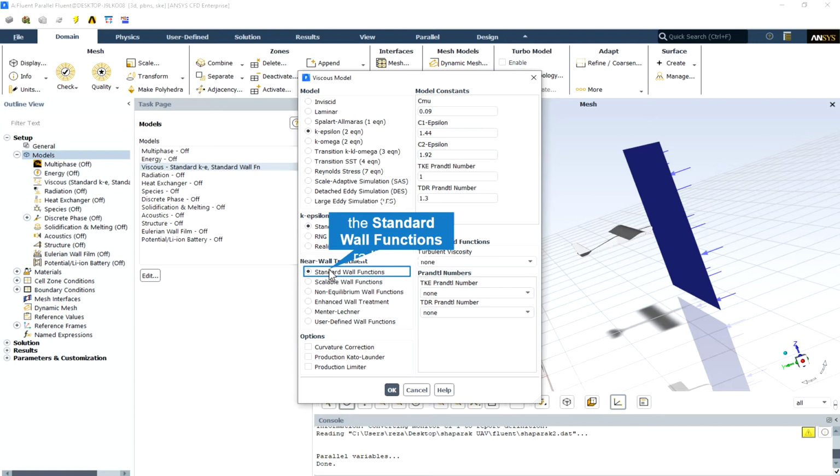If the k-epsilon turbulence model is used for the simulation, it is not possible to simulate flow vortices near the walls. A wall function must be defined to investigate the fluid behavior near the wall. So we should select one of these options. These wall functions are near wall analytical flow profiles obtained by explicitly solving the near wall flow equations. So they are more accurate than numerical methods, of course in simpler models, I mean.